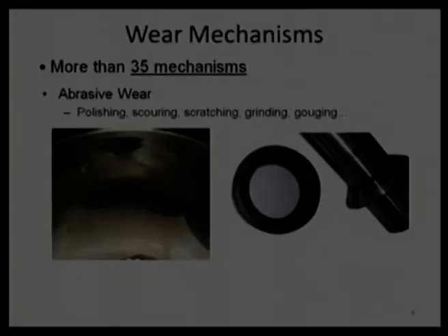Once this layer is getting deposited, carbon graphite layer is getting deposited on the stainless steel surface, we are going to reduce coefficient of friction and subsequent wear. In other words, initially there will be high wear because of the transformation of the layer from carbon graphite to stainless steel, and subsequent to that wear rate will come down, friction will be reduced. We talk maybe the coefficient of friction initially around 0.3, 0.4, and subsequent to transfer of this layer, coefficient of friction may be reduced to 0.2. So, almost 50% benefit is on that, and we desire it.